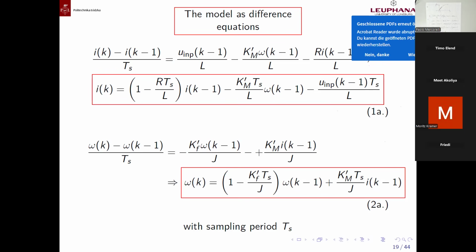If TS is very small in this context, we don't have these changes. We will come back to this. This means keep in mind that the model depends on TS. TS should not be so small, but of course should not be so large. We will see why, but so large is intuitive. Otherwise, I lose what happens between one measurement and another one, one prediction and another one.